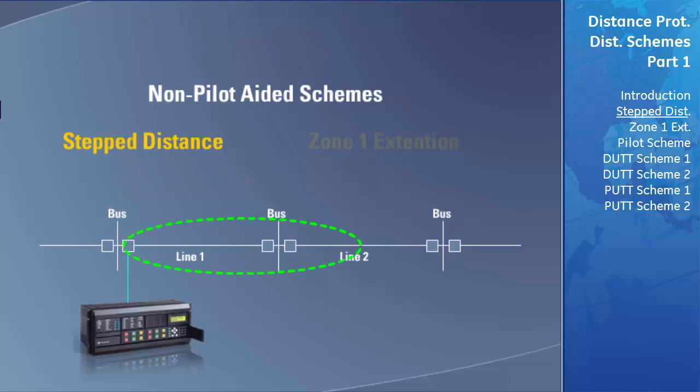The second zone of protection is set to overreach and extends from the beginning of the transmission line past the end of the line into the next adjoining transmission line. Zone 2 is usually set to 120% of the impedance of the transmission line. Zone 2 is set in this manner so that it can detect faults occurring in the end zone area that zone number 1 cannot detect. Zone 2 is also always programmed to have a time delay set between 250 milliseconds and 400 milliseconds.